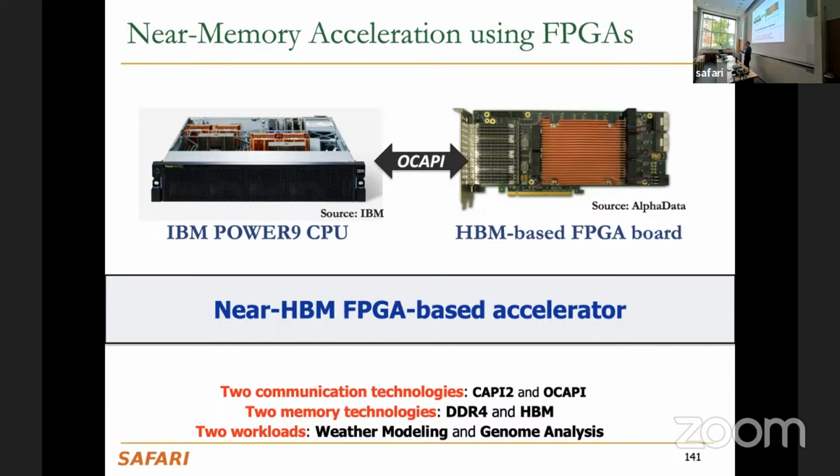In a CPU today, we have a lot of control overhead, right? You need to fetch the instruction, decode the instruction, and do a lot of bookkeeping. Execution is a very small fraction of the energy and performance. You do a lot of other bookkeeping stuff to actually execute something. Whereas in an FPGA, you can program the circuit so that execution is, hopefully, the biggest part, and you don't have the control overhead as much. In ASIC, you get rid of almost all of the control overheads. So it's good to think about that. In general purpose systems, you have a lot of control overheads. So here, we get rid of a lot of that.